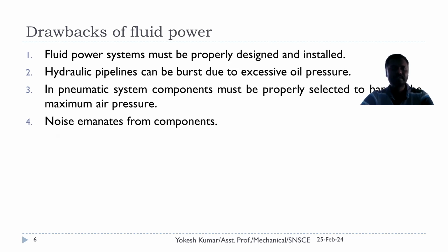The second drawback is that hydraulic pipelines can burst due to excessive oil pressure. There may be a chance of overloading of the system, which leads to excessive oil pressure and creates bursting of tubes in the circuit. The third disadvantage is that pneumatic components must be properly selected to handle the maximum air pressure. If this is not done, it leads to failure of the system.